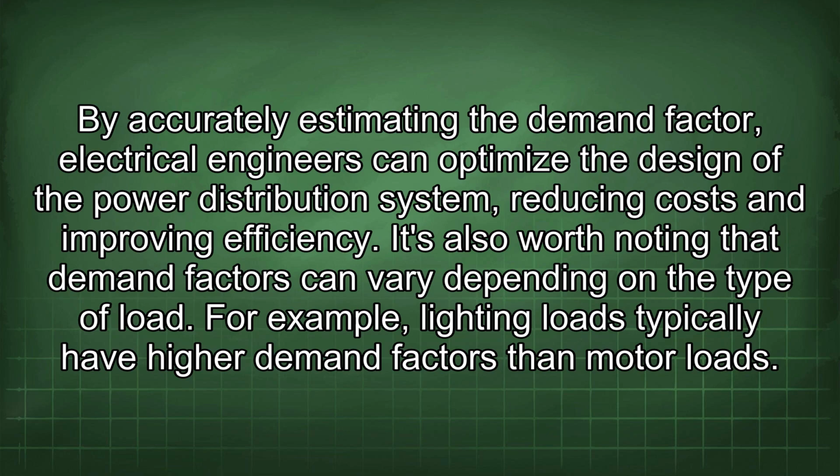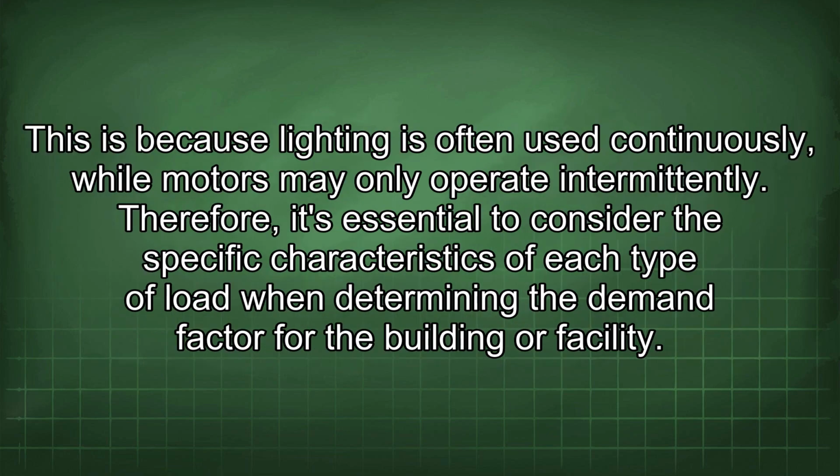For example, lighting loads typically have higher demand factors than motor loads. This is because lighting is often used continuously, while motors may only operate intermittently. Therefore, it's essential to consider the specific characteristics of each type of load when determining the demand factor for the building or facility.